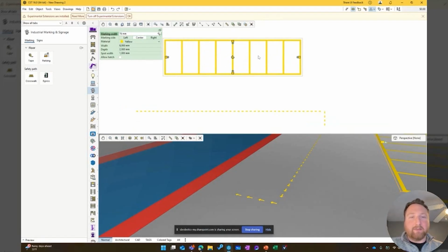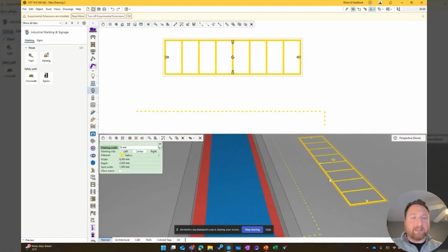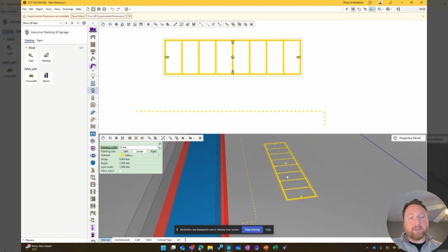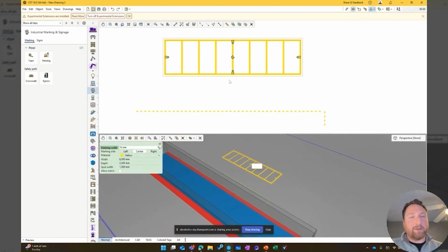So whether that's in-floor mounted contact that the robot has to pull into, or back into sort of extending charge points, you can use this tool to really easily define how big those spots need to be, drop them into the layout, and once again, show your customer, this is where I'm planning to do all this charging work. Any issues getting power there, start those discussions early, and show that you have that space reserved.